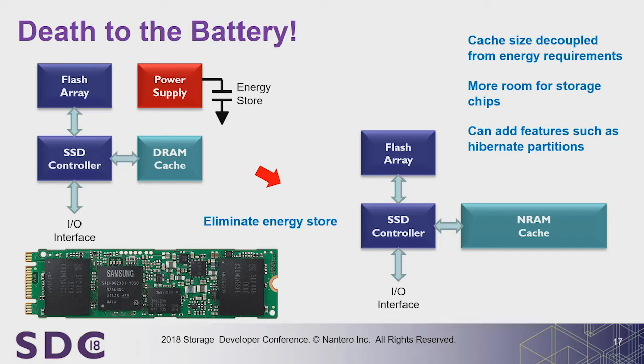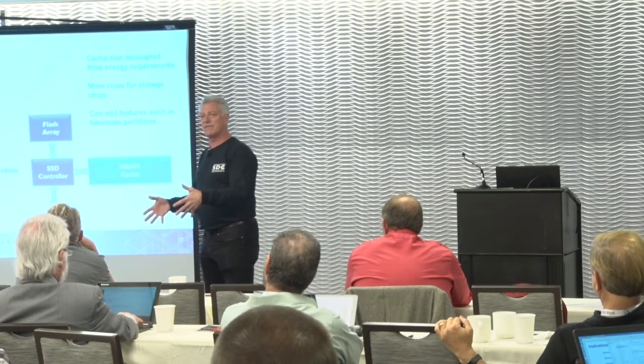That controller is going to have typically flash memory for the mass storage. That's the general architecture of an SSD. But that could also be the rotating media for your hard drive. But hanging off to the side is that cache. And that's the weak link, of course, that you're putting data in that cache, you're doing command reordering and so forth, and you're sensitive to data loss.